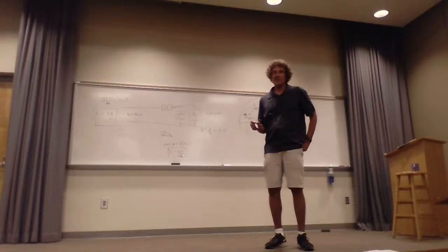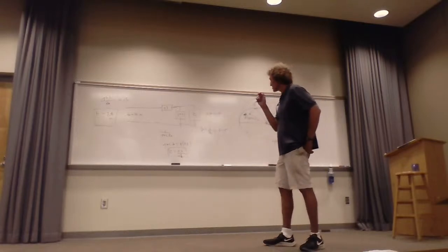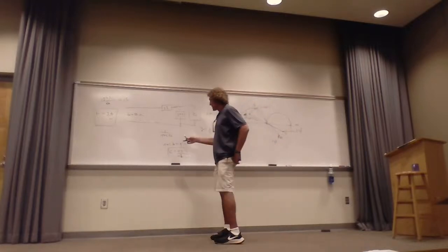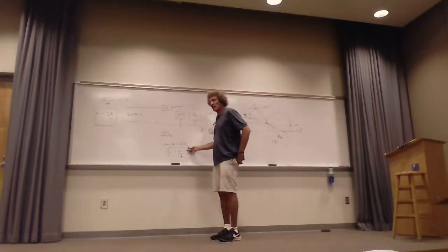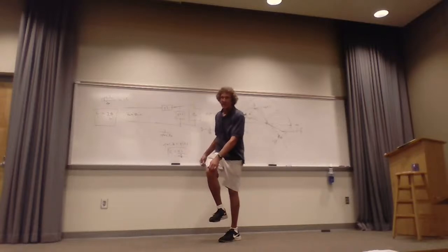Now, something I'm going to state. This impedance matching only works for a very small band of frequencies. Remember, the minute the frequency starts changing, then these values, the j0.2, start changing. You with me? And that's why you got to be careful.